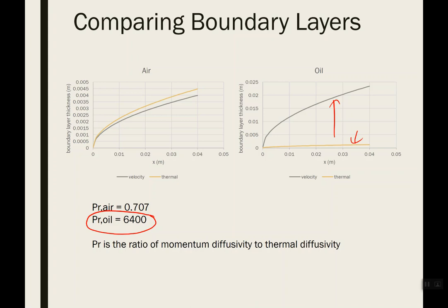So we would define the boundary layer because under ideal circumstances, that velocity boundary layer would just asymptotically approach the bulk velocity. So in order to make that more of a finite thing, we just say when it gets to 99% there. Similarly for a thermal boundary layer, if the table is heated and there's heat transfer going on, then you're not just going to go suddenly from the table's temperature up to the bulk fluid temperature.